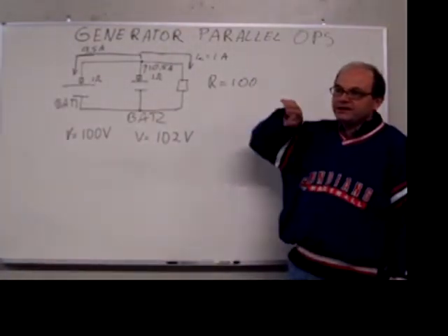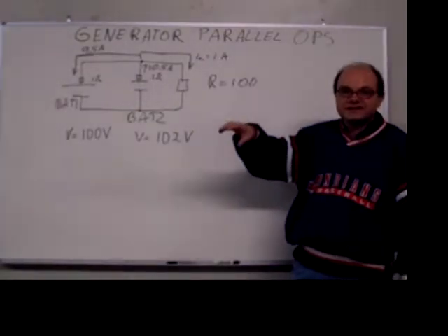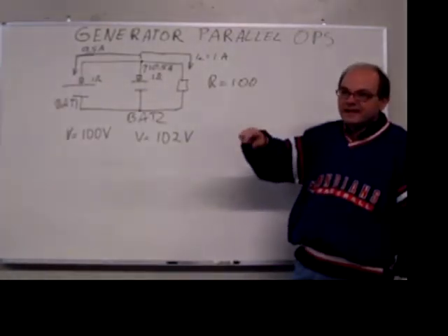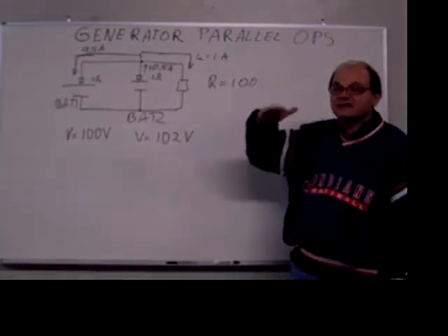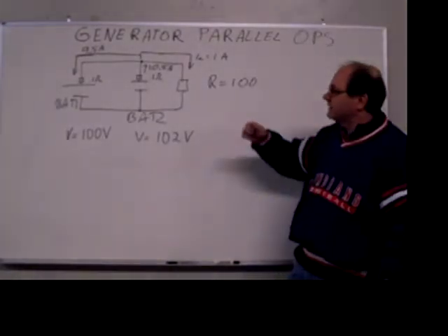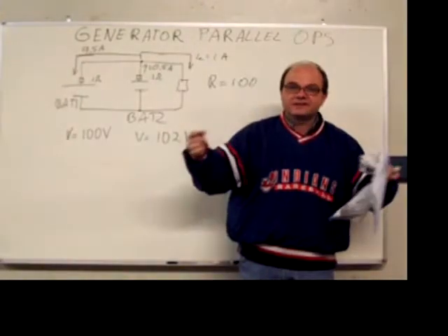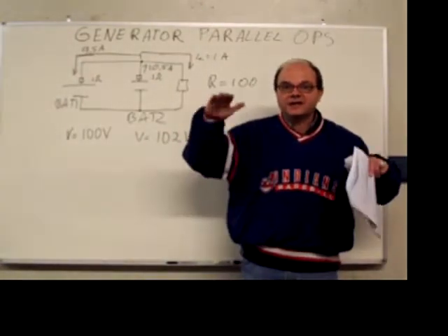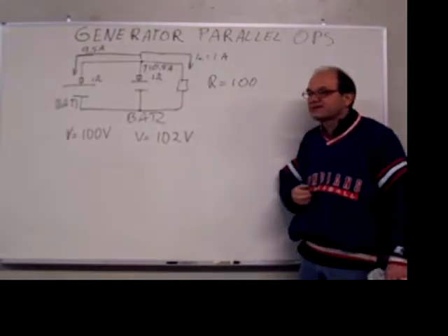And that brings out the excitation voltage out to your generator set, to the excitation coils. And depending on what voltage you're setting, that's how you can basically regulate the voltage output of the unit. So each unit would have to control the other unit's voltage output until they actually come into sync. We could build the circuit board for this.